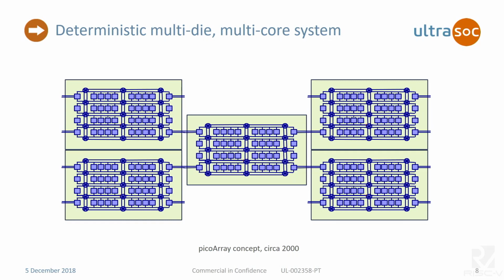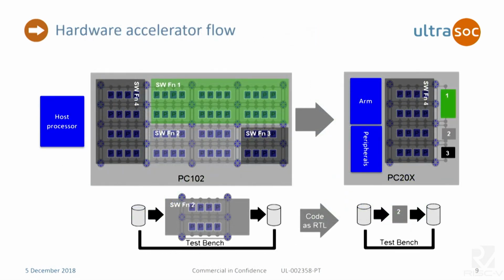Because you had the compile time interconnect, you had no runtime arbitration. If it compiled, statically compiled, that meant your system would operate in a deterministic manner. And so you could exploit that by taking the sea of processors here, instantiate some software functions like Viterbi's or turbos, and then the next generation of the chip, you hardened it and used the same verification suite as you did for the software implementation. That meant you saved on your verification time, and you got a smaller die.